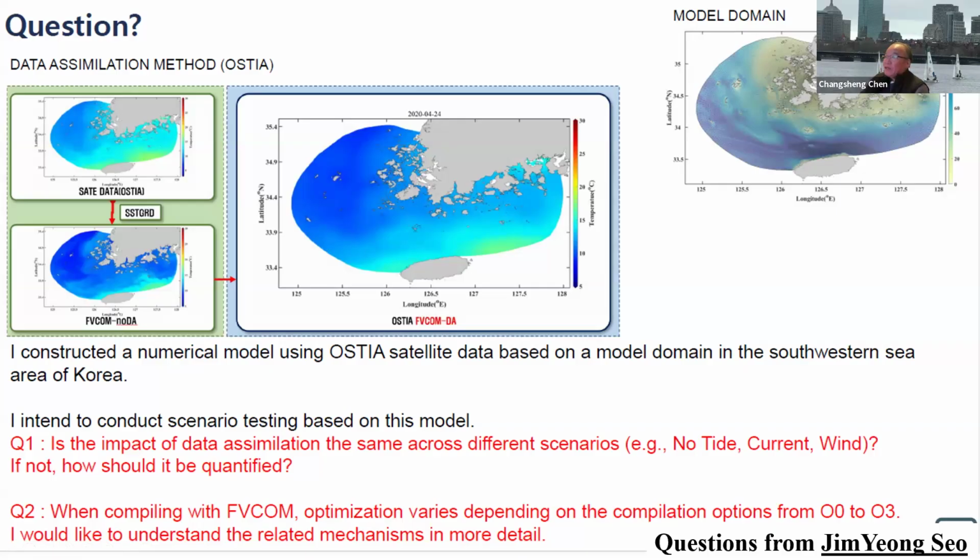For example, you show the whole tidal elevation, you show a wind-driven circulation, you see the whole sea level changing, the whole circulation changing, temperature, salinity. Then you compare with observation. Observation shows, say, 1 meter, and my model only shows 0.8 meter. So you say, okay, I want to improve the model. Then you can use data assimilation. However, one bottom line is: don't use data assimilation to create any results you want to see without getting a more robust model.